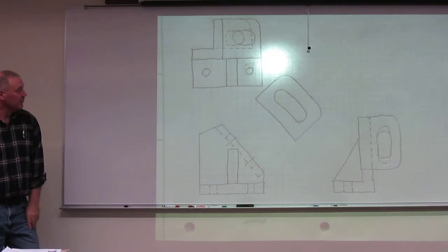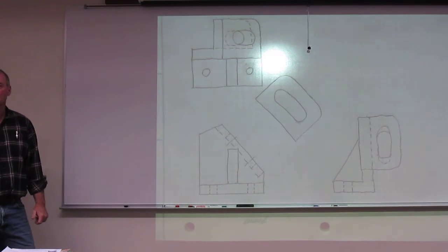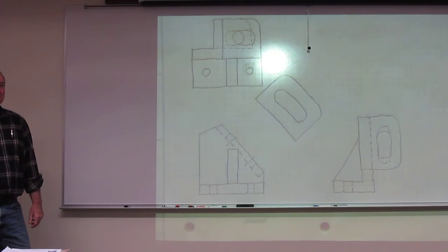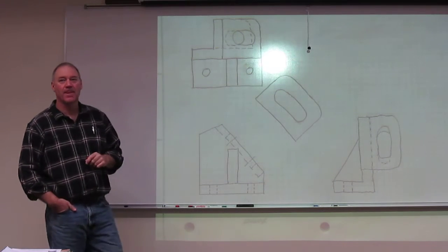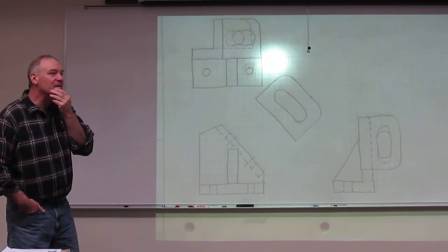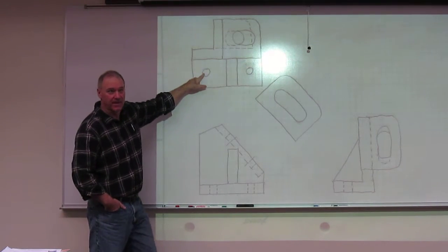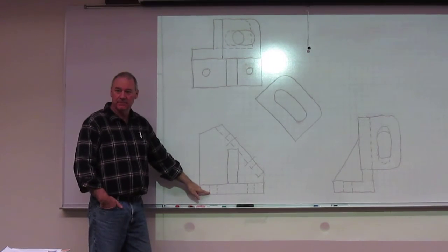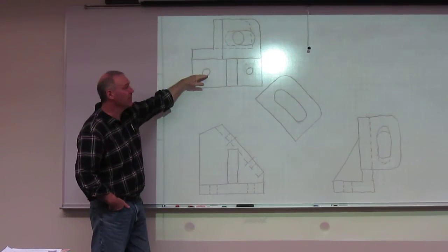So that's one problem with it. The other problem is, how many views do we really need? Okay, and what do we need them for? Lisa's saying we need 3 views. But let's look at the geometry. This base plate has 2 holes in it: circular view, rectangular view. Okay. Height, width, depth. I would say though that base plate is done here.